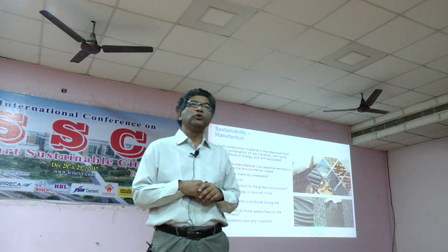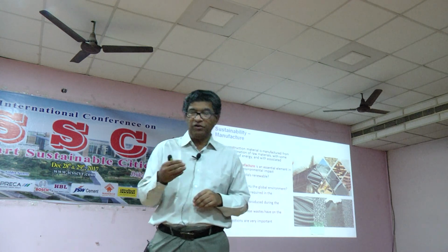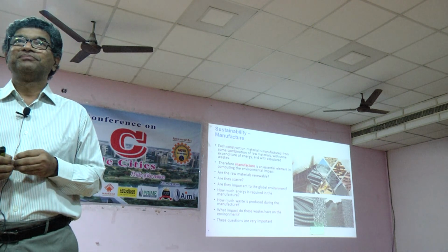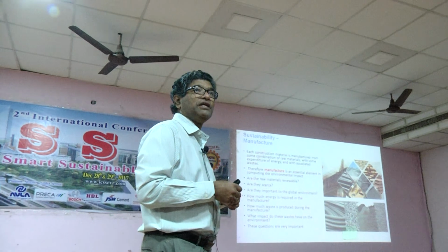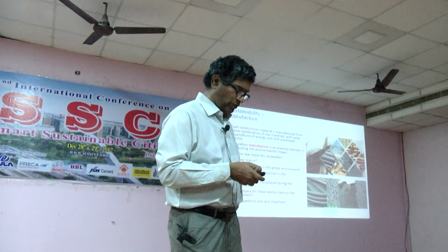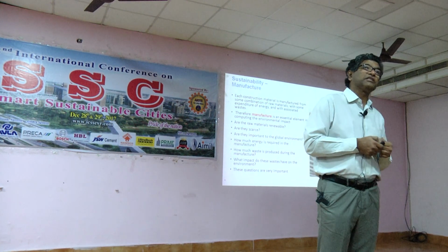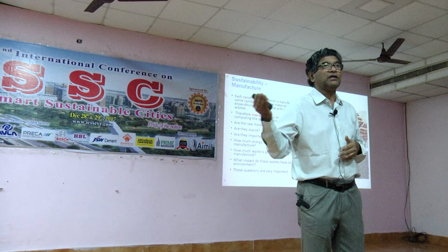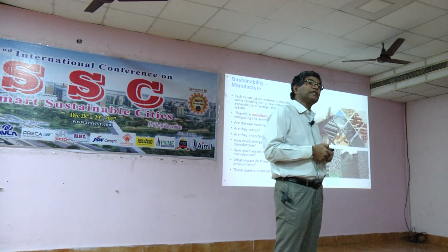If I say I need 32 cubic meters, the fellow will be sending not 32 exactly, maybe he will be sending 34 or 35. Where should I use this 3 cubic meters extra? This fellow will simply take the truck and dump it away and go, then it is a wastage. But if there is a good intelligent project manager, he will try to take that and use it for some other works of his, like grade slab concreting and all that. But some wastage is there in concrete also.